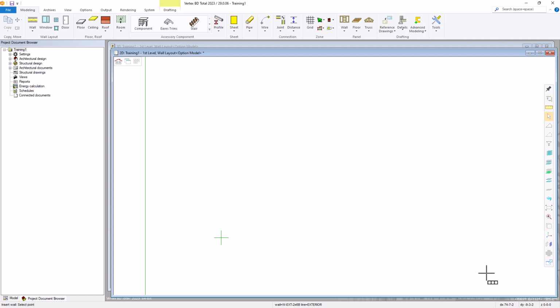Over on the right corner are the X and Y coordinates. Those are updating as you move your cursor. If we move it over to the crosshair, you can see that that's the 0,0 origin point. So we'll want to pay attention to this as you're drawing walls. We'll go through a couple of exercises on multiple ways to enter walls. We'll start out with a simple X and Y coordinate input. So let's go ahead and start. You can select any point. Click a point.